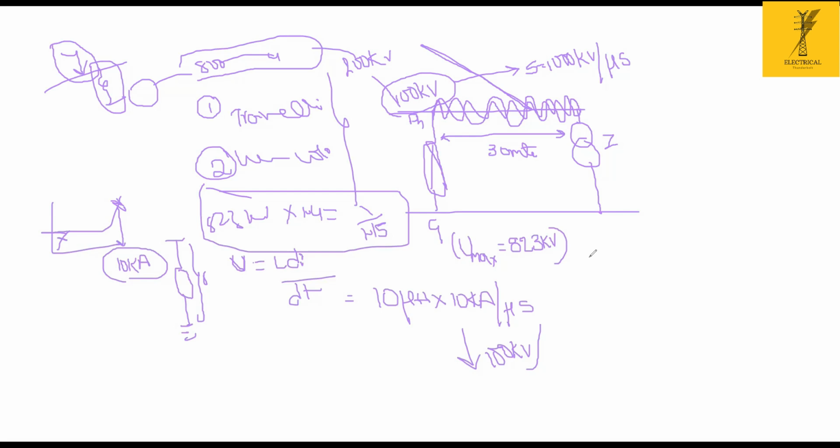So with lightning arrestors, as we discussed so far, we are checking the stable continuous operating voltage, the MCOV (maximum continuous operating voltage), and the rated voltage. We also talked about the protection level of my lightning arrestor with a factor of 1.4.